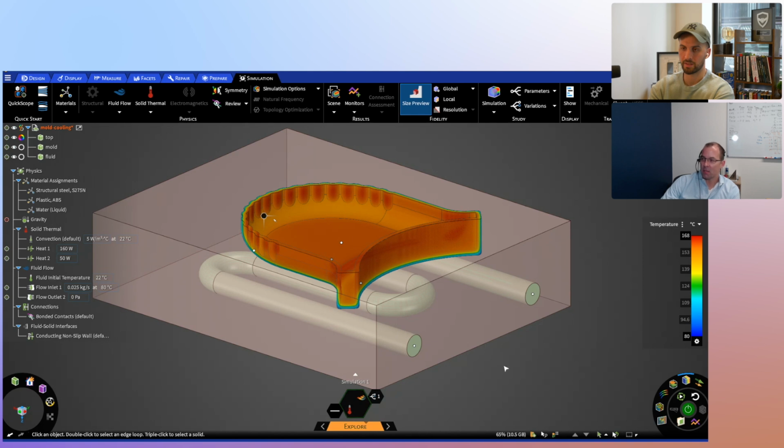Forced convection, this model right here, we can get within 5%, no problem. It's just a matter of getting your fidelity up there so you can capture the proper heat transfer coefficient right at the wall interface, and that's that. Has Ansys talked about the solver behind that technology?